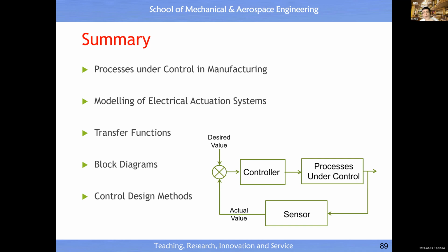The first design method allows you to design a stable system. The second allows you to design a control system with a desired performance. And in case tuning the existing parameters cannot achieve the control result, you add a PID controller or a lead-lag compensator.